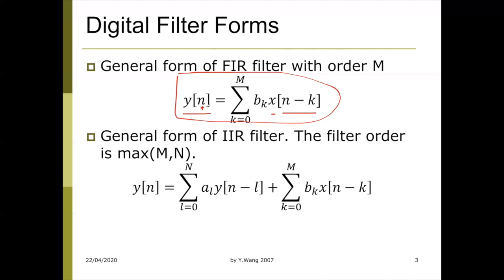So the output signal is calculated from various past samples, and not just the past samples, but each is also multiplied by a factor d_k. So for each different past sample, you apply a different coefficient. So this is the FIR structure. This structure tells us the filter only calculates using the input signal. This is a finite impulse response, because if your input is finite, the output is going to be finite, because there is no more information you can get from the finite input.